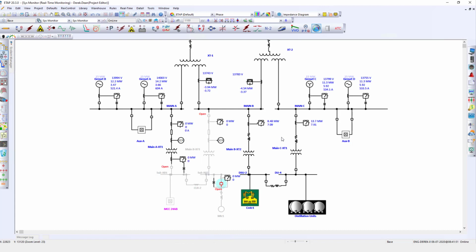In this case, we have an unexpected result. Instead of the motor energizing, we see a large portion of the network is de-energized, and there is an error indicating that the command was unsuccessful. Note that this is due to the overcurrent relay here.